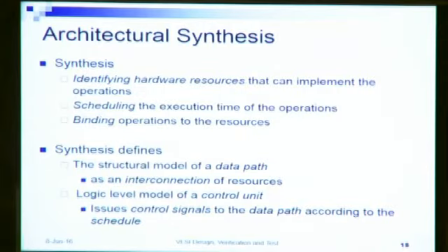So what we're basically trying to say is that the control unit will issue control signals to the data path according to the schedule. So it will control which registers, which functional units, should be activated at each time step, so that the correct sequence of operations is performed according to the prescribed schedule. Okay.